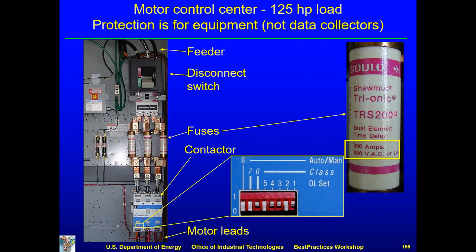They actually pull the wire loose and just stick it through a donut. It's a coil, and it picks up the magnetic field, the EMF around the wire, and transduces it into a current. So that's how you measure the current on the wire. For portable meters, they have them that open up like a clamp, and you just clamp them around it. So you clamp on this one, this one, this one, and then you get voltage.